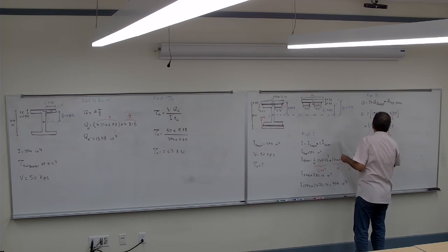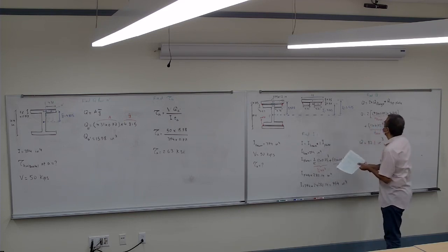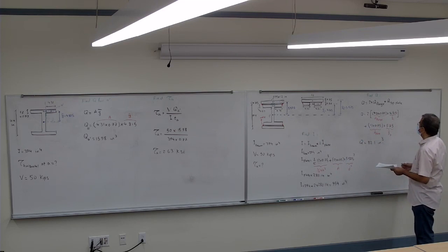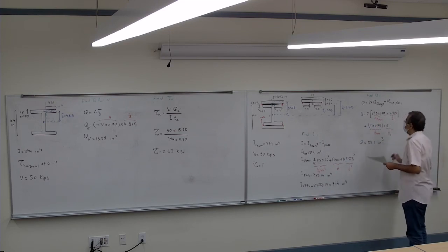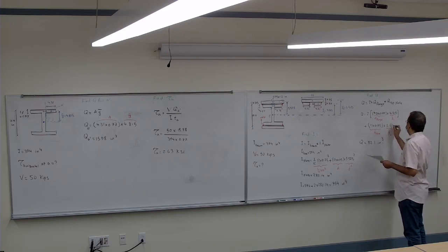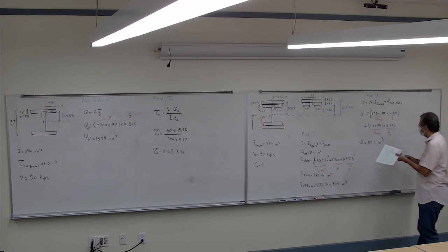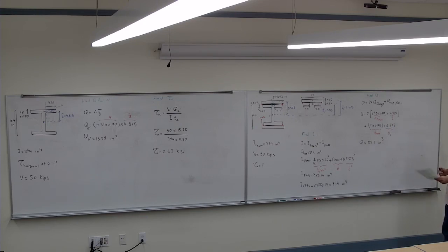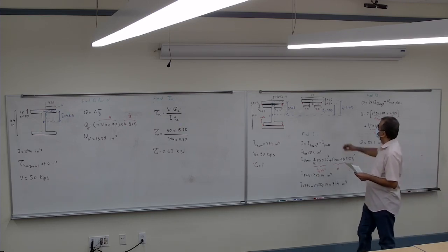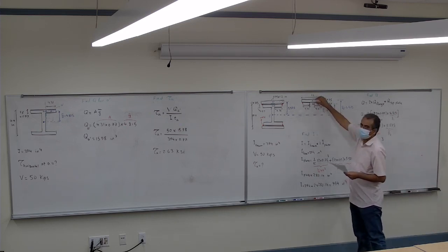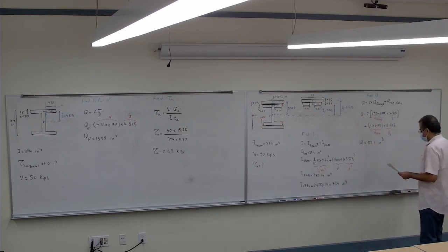You said the y bar was 5.575, but you wrote 5.75. Yeah, all right, 5.575, yes. Thank you. And then, even though the plate adds height, since it's a separate thing, we don't adjust y bar for A. Oh wait, no. Never mind. You have to calculate for this area and then for that area separately, once I said it out loud.